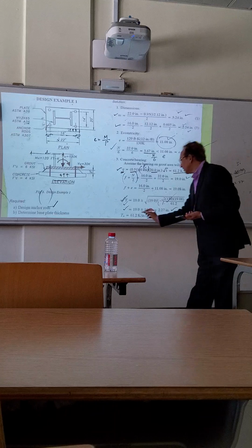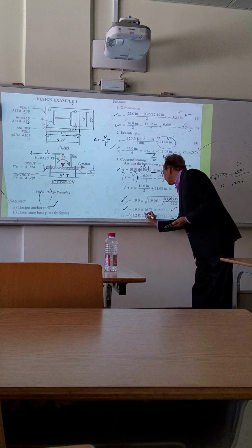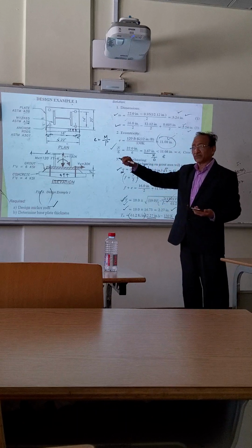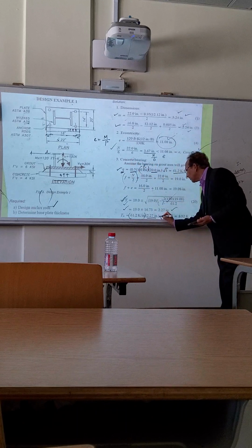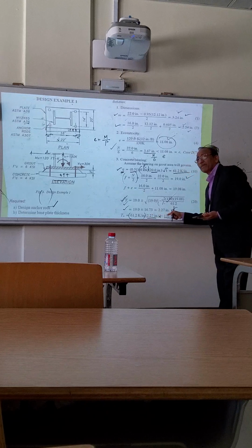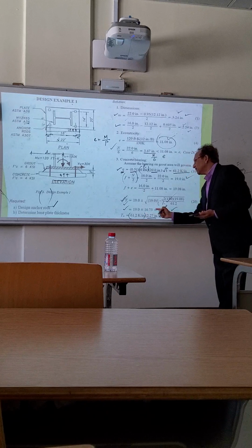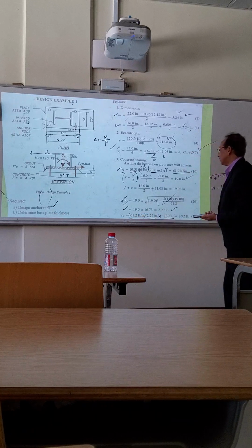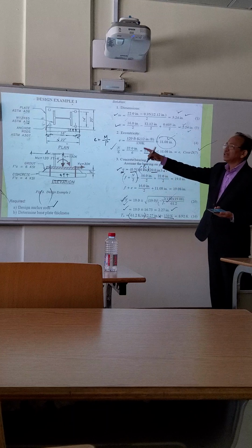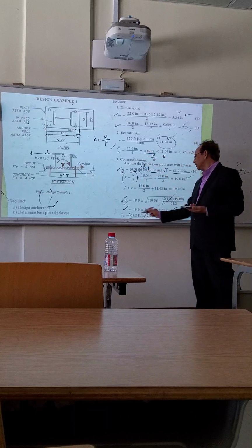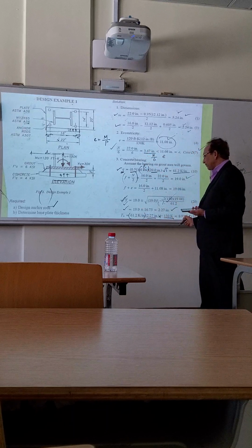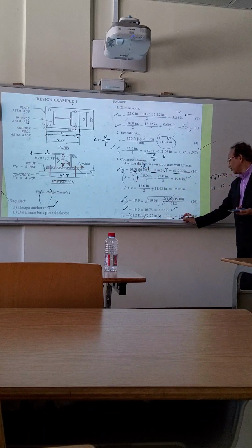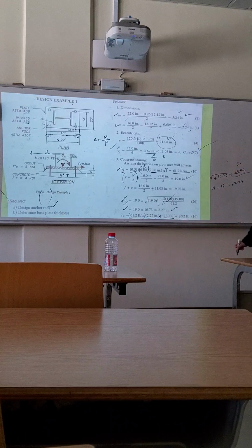Okay. So this is pressure of concrete. This much is the length, and we are calculating for only 1 inch per inch. So you can say for 1 inch, this is area. Stress, which is kip, and then already we multiply by 1. So you get, and minus 130 is the load. So this whole thing is just in kilopound. So finally, the force on these rods will be 8.92 kilopound.